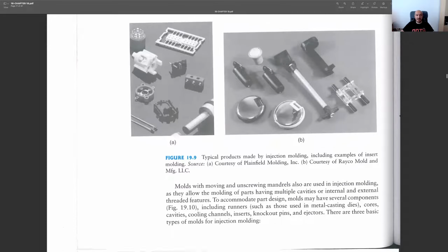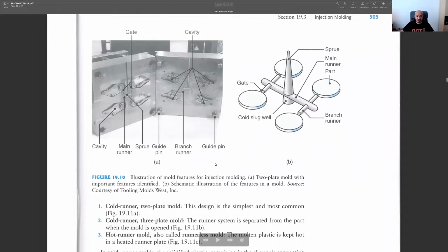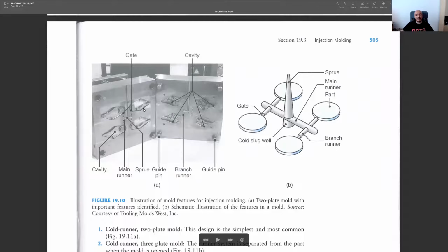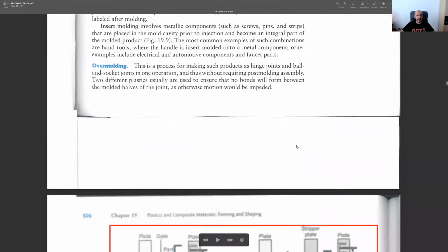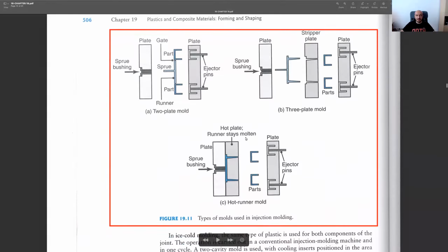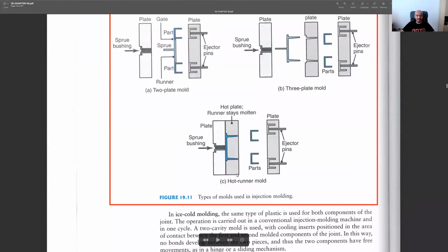So it's highly versatile. You can produce various shapes, and even in the same die, you may produce, let's say, 4 pieces at the same time. Since the material is in the state of liquid, it can easily fill these cavities, and later, once this injection molding is over, you can take this part out of your die and do some cutting operation and just be left with these desired parts. This is another example using different types of dies, but the idea is the same.